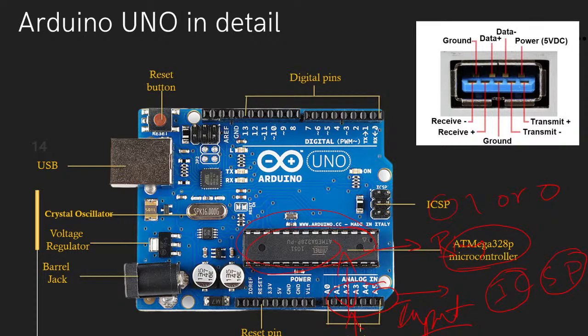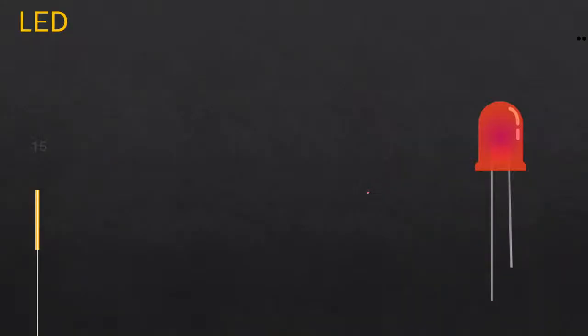If I want to use one Arduino board, it's okay. If I want to use another Arduino board, I have to take a separate USB cable and connect it to the laptop. I think that is not a good option, so we can go for something else. We can use the ICSP pins. We can connect to the ICSP pins of the other Arduino, and we can serially program that Arduino also. With that, we can power that Arduino and program it using the ICSP pins.